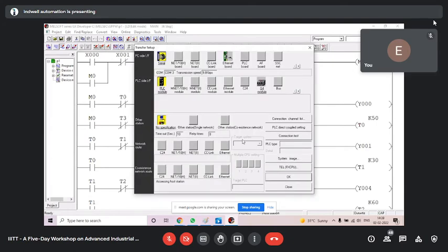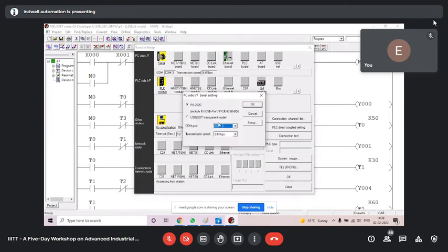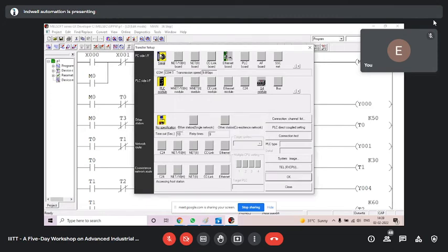this has been opened, and here I had already selected COM port 3. But by default, actually, it will show you COM port number 1 like this. When you connect your serial cable to the 9-pin serial port, then it will be by default COM port 1.